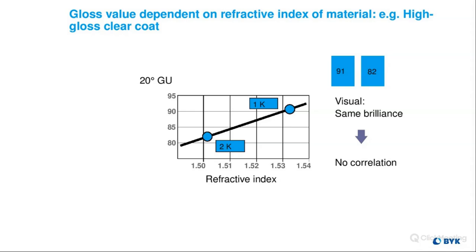Now, you mentioned above 100 gloss units. That's only the case if you had something very different from your other samples. So again, if you had plastic samples and then you brought in a metal sample, obviously the metal can't absorb light, so it's going to reflect a lot more light. So you'll get values over 100. That could be a case. But for the most part, you don't necessarily see any point where the gloss meter won't give you a value at all.